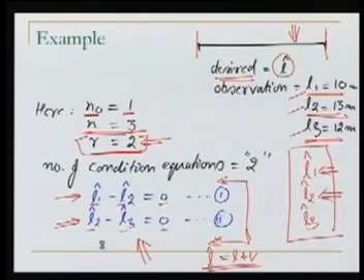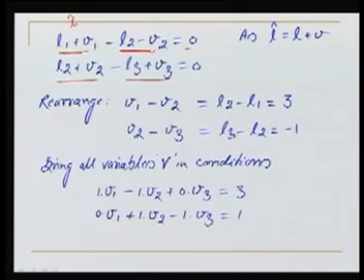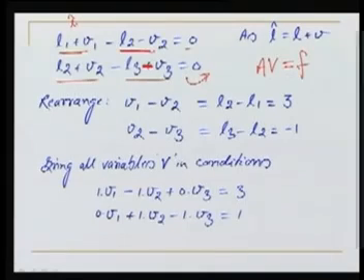Now minus L3 hat over here, please check, this should be minus, this is not plus, this is minus. Well, having done that, we want to rearrange these terms. Rearranging means, because finally we want to write it in the form AV is F, we are taking all the constants on the right hand side. We are putting the V terms, the residual terms, on the left hand side.